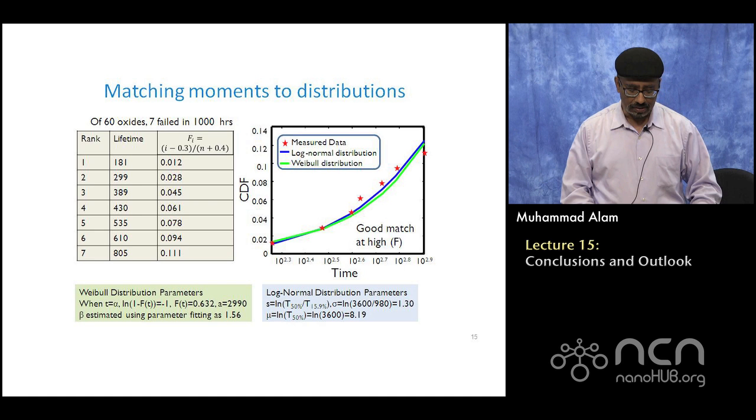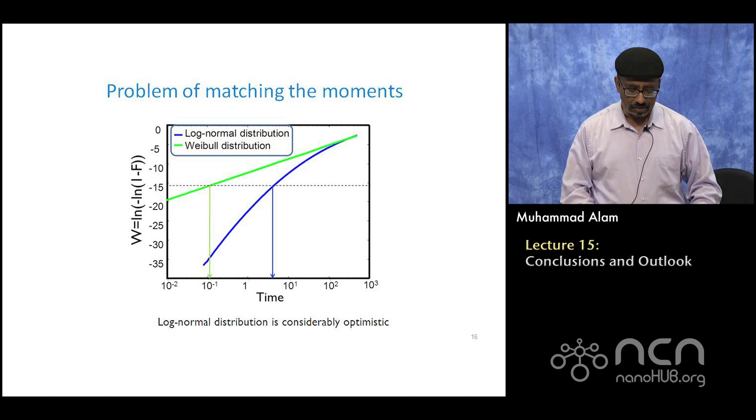Because in the lab, you may be able to test only a few of these things because it's so expensive. Let's say you have 10 wafers or 10 experimental samples that you can test, but you will be selling hundreds of millions of these. In an iPhone, for example, the transistors will be hundreds of millions. And based on what you decide your distribution is, it is going to tell. So, for example, compared to the previous one, in this plot time is plotted in a log, and this is the failure distribution, just plotted in a slightly different way.